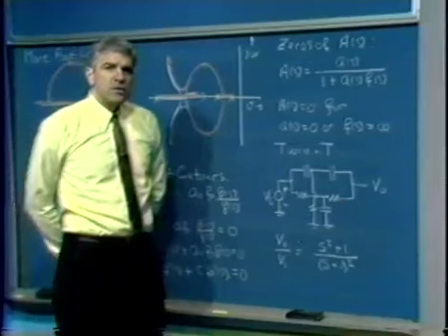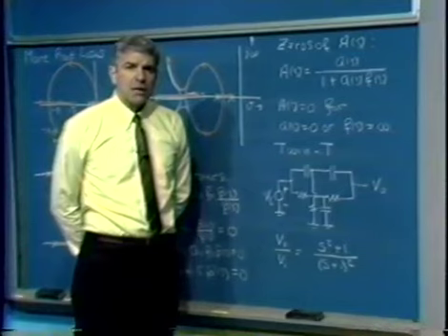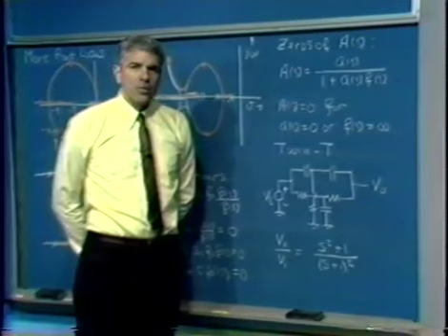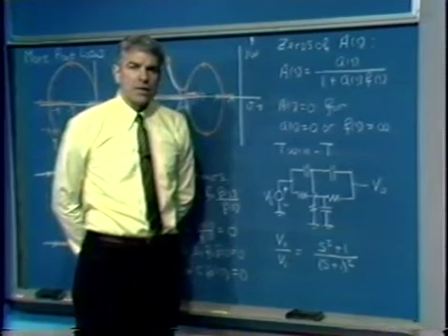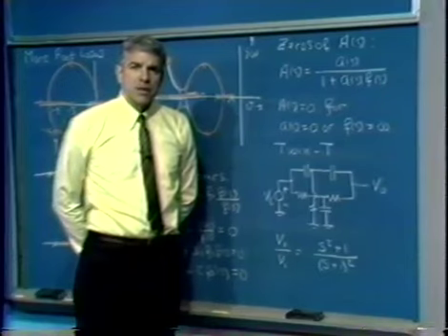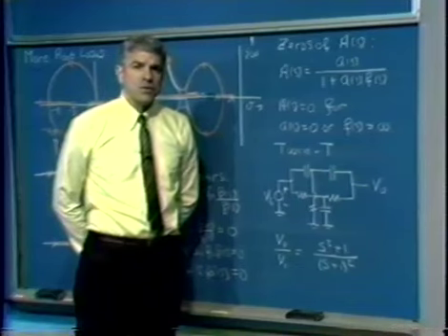While we can determine the stability of a feedback system, and in fact tell how close to instability we are, those sorts of measures of relative stability, simply by looking at the closed loop pole locations, clearly an overall understanding of the response of a system requires the zero locations as well. And I'd like to do an example that shows the dramatically different performance we can get from a single system, in other words, a system that has the same pole locations depending on the location of its zeros.